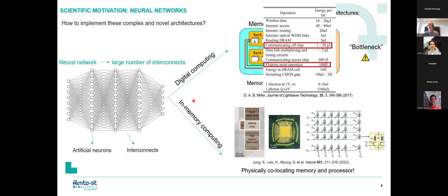The general view is that we can get around this challenge using a concept called in-memory computing. In in-memory computing, the neural network really is implemented usually as a true physical mirror image of the neural network computing concept, i.e. neurons could, for example, be nonlinear units, but especially all of these connections are realized, for example, in this electronic circuit using something that is referred to as a resistive crossbar array. And then simply using the accumulation of currents when applying voltages at these inputs and using the accumulation of currents at the outputs, the resistors or their conductance represents these weights. And now you get rid of this shuffling of memory from external RAM into the processor. So that's mostly the approach that we're trying to implement.